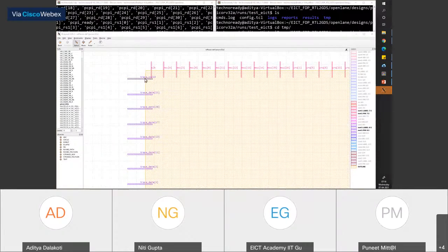So you have this horizontal IO. Earlier, it was up to the outline of your design. Now it is extending beyond the outline by 10 micron. Similarly, in the vertical direction, this pin is extending beyond the boundary of my outline by 5 micron. So if you create certain sub blocks within a bigger SoC and you want the pins to extend for better connectivity, then you do an extension on those pins.